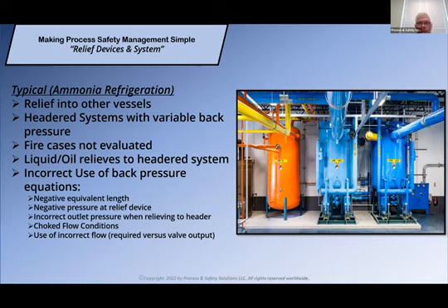Fire case is not evaluated. For example, if you look at this picture to your right, there are 3 vessels sitting there. All 3 vessels could be subject to a fire. So now we have 3 vessels that are relieving essentially as that fire has taken place. Now we know for the most part in a fire case, the relief valve will open and close as that pressure builds, et cetera. So not all of them may simultaneously be relieving at the same time, but you could have 2 of them relieving. Well, when the other one builds enough pressure, there's going to be back pressure on that relief valve, not allowing that relief valve to lift as it should at the right pressure as well.